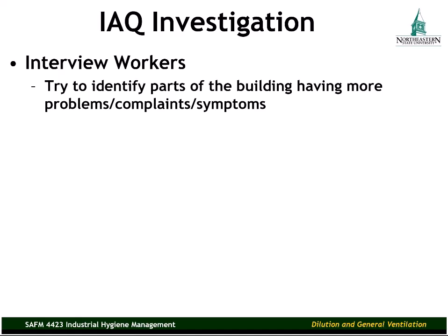It could be that the ductwork supplying those offices or that section, there's a problem with that ductwork. Maybe it's not moving enough air. Maybe there are contaminants in that run of ductwork. So interview your workers, try to identify parts of the building where the symptoms, the complaints seem to be concentrated.